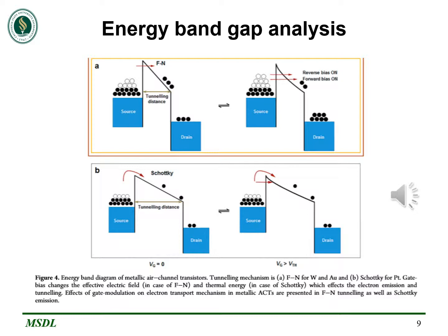Furthermore, under the influence of gate voltage, the energy level bends slightly downward by controlling barrier width, enabling few electrons to tunnel through at a lower energy level, as shown in figure B. Therefore, we observe Fowler-Nordheim tunneling when the gate voltage is different from 0 for platinum. However, the bending effect is not significant due to the higher work function and electrode gap, and hence the dominant mechanism remains Schottky in all cases for platinum. As the Schottky emission is mainly due to thermal energy, the device turns on or off depending on the effective thermal energy generated with gate voltage.